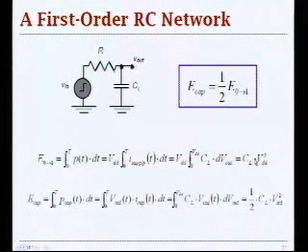So what happened to the other half? Right. It basically got dissipated as heat on this resistor. So the energy that is provided by the source tells you about the amount of energy you need to perform a useful transition and the amount of heat that you have dissipated in your circuit. So you always have that the energy to perform some useful charge or discharge operation is equal to half of the total energy, where the other half is dissipated as heat.